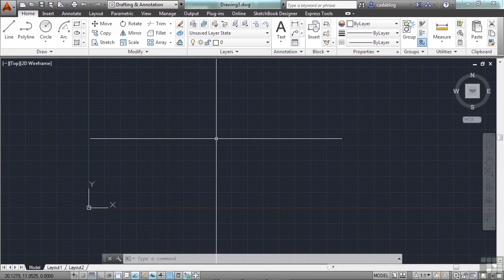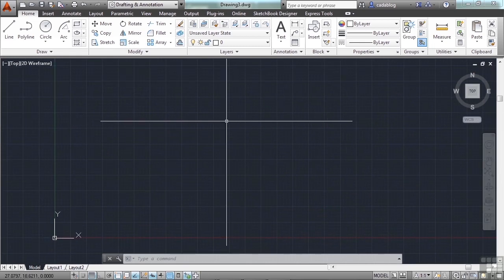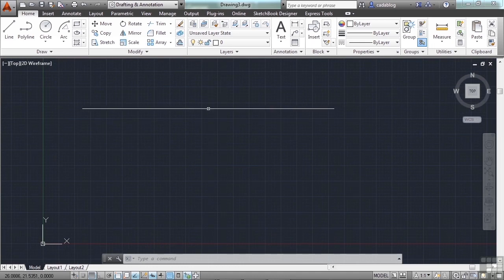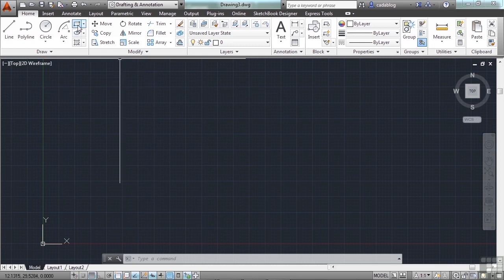So in this drawing, again, we're going to create a basic, very simple landscape plan view of our home. We don't have any numbers to go by or anything specific, so I'm just going to provide you with those. First, we're going to draw the outline of our house, and we're going to make it with the rectangle command. A lot of times, the landscape architect will have nothing more than just the outline of a house to design around. So start with the rectangle command.